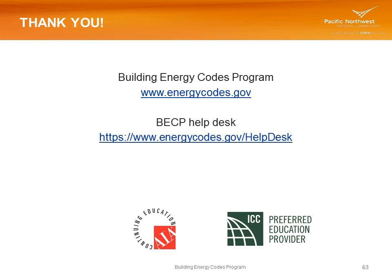flipping open my code book right now. I think we do have some listings for water source heat pumps, and so those, water-to-air, water loop heat pumps would apply. And actually, there's a separate listing in Table 403.2.3 for groundwater loop heat pumps and requirements in both the heating and cooling modes. So there is actually a separate listing in the table for ground source heat pumps, and maybe I'm not understanding the question as far as the distinction. So they are listed in the code. So maybe that person's referencing the residential code. I'm not sure. Yeah, so it may not be in the residential. It is in the commercial.